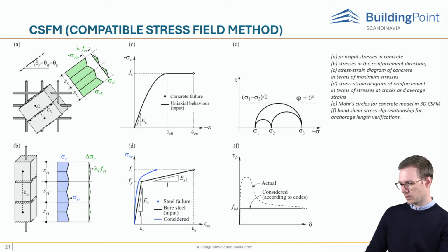The reinforcement bars are linked to concrete volume finite elements through bond elements, allowing for slip between the concrete and reinforcement. And as previously mentioned, it should be noted that 3D CSFM is not suitable for simulating plain concrete due to the absence of tension, which may result in misleading deformations and model divergency.